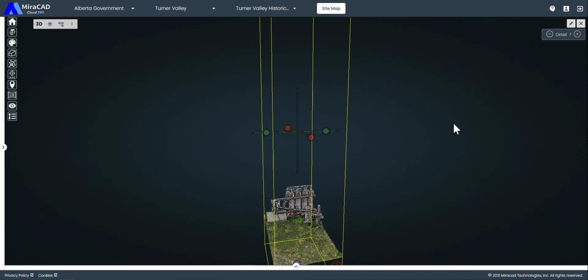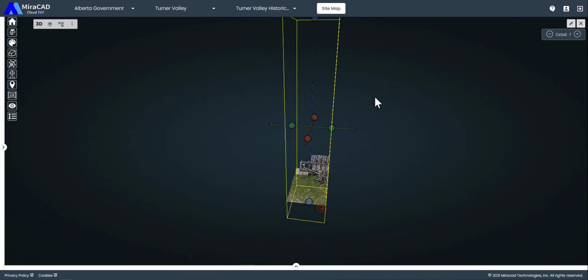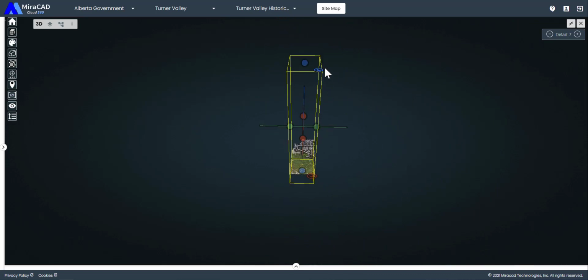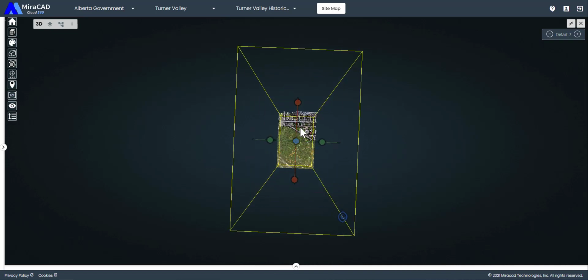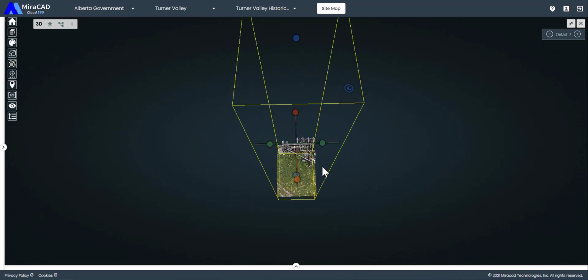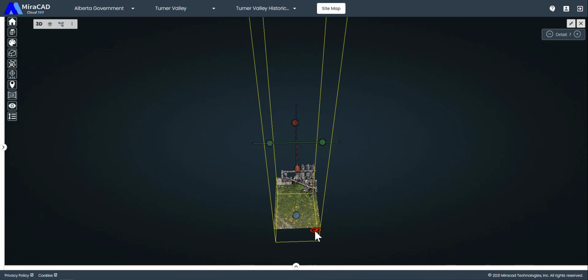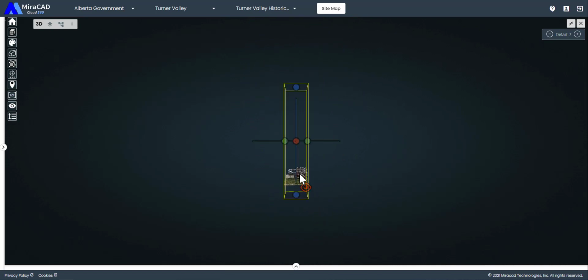You will notice the blue eye on the top of the clipping box. If you click on this eye, our view will be reoriented to viewing this clipping box volume from the blue axes. You can now select the red dot and drag it to remove unneeded data. Now let's rotate another side of our cube until we see the red eye. Click on the red eye to view our area along these axes.